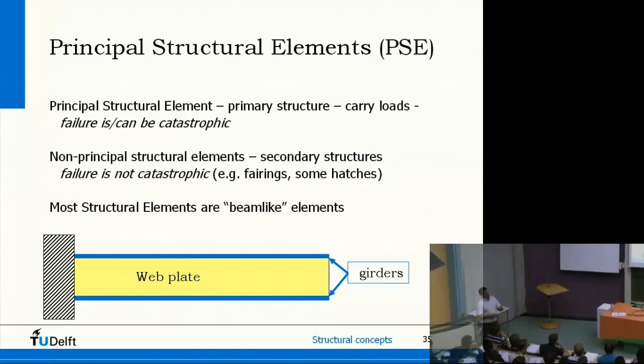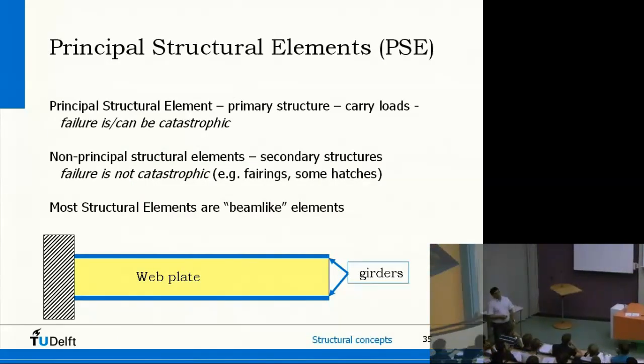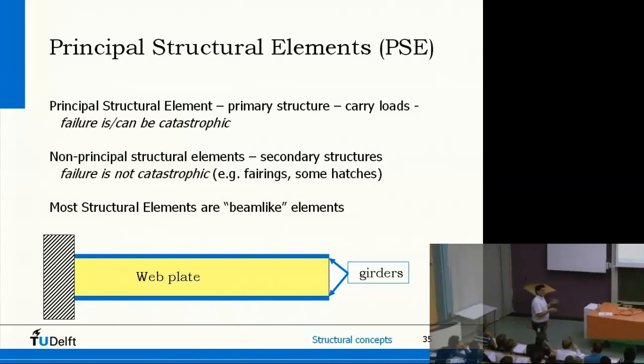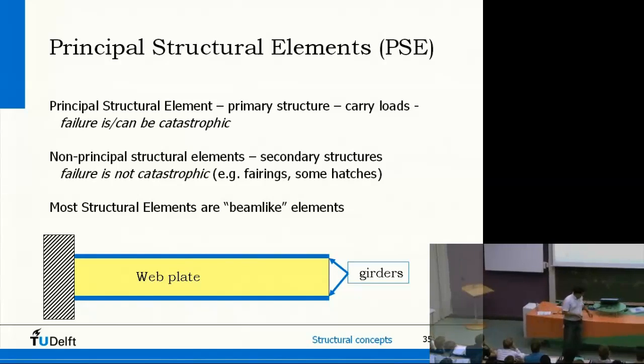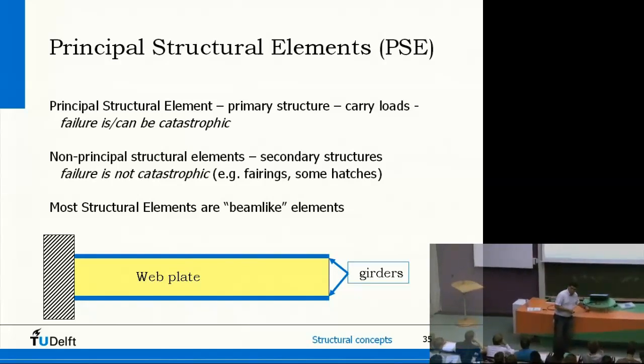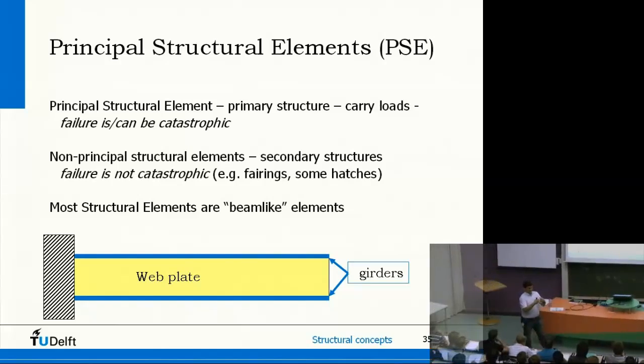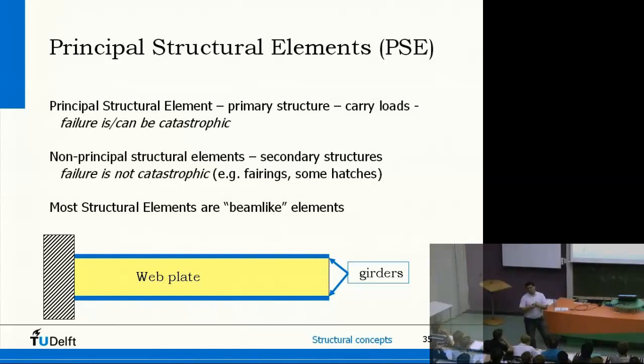That's becoming, by the way, more and more a problem if you are working with composites. Composites are much less flexible in these kind of things than the metals. That's also why, for instance, the 787 had quite some problems during the assembly. As soon as you have a mismatch in dimensions of a few millimeters, it is much easier for a metal to accommodate that, to counter that, than for composites.